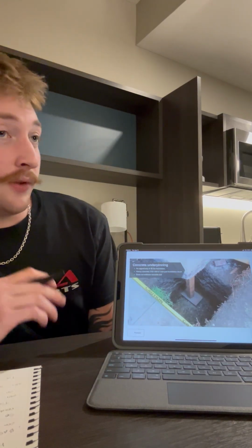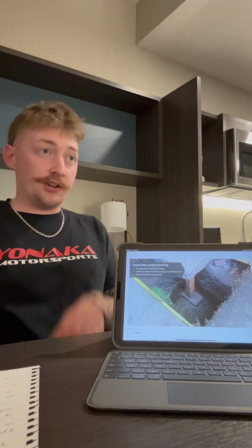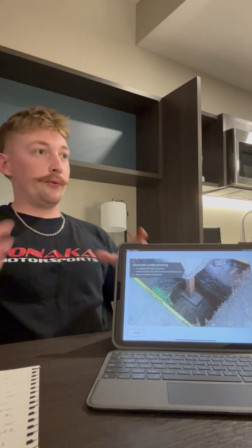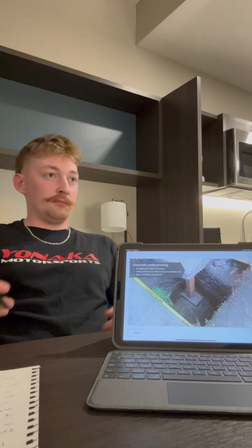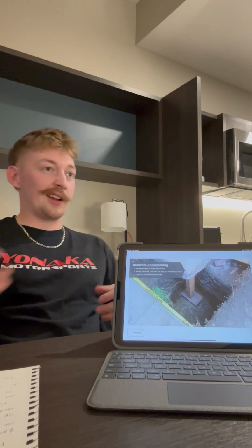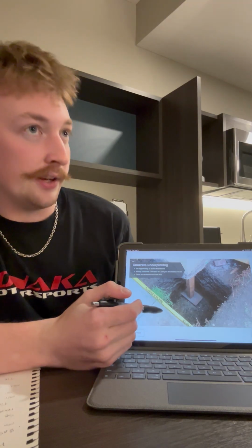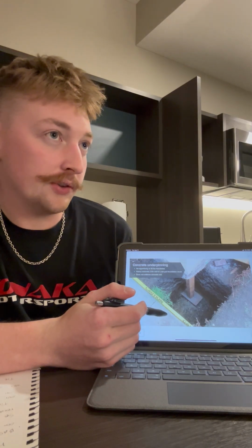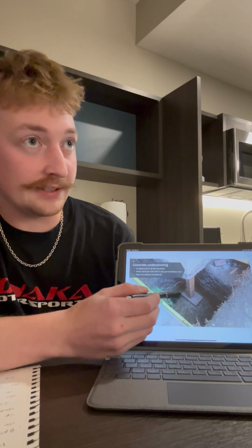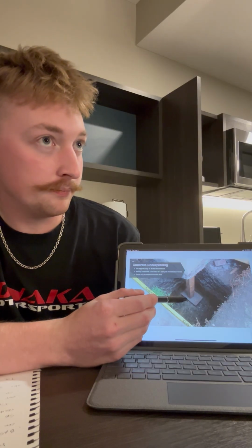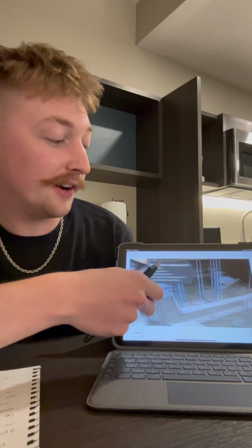Love it. So the second is concrete underpinning. Let's say you called an engineer out, they might say we want a bigger footing, more surface area, similar to when it's snowing: you have sneakers on and go right through the snow, but if you had a snowshoe, you'd sit on top. But what they didn't realize is your house is already sinking, right? Concrete weighs 100 to 150 pounds per cubic foot. So this is literally tying an anchor to an already sinking ship. Most of the time this is going to make your house sink faster. That's terrifying. Pretty terrifying, right?